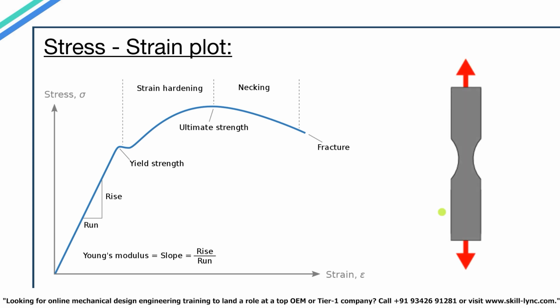So the way this works is, if you want a stress-strain graph for steel, then a steel rod will be selected and it will be subjected to tension loads to increase the stress of the steel rod. And they will keep increasing the stress value till the material breaks, and during the process a device will be used to keep track of the strain values in the rod. Then using all the stress and strain values, the graph is plotted.